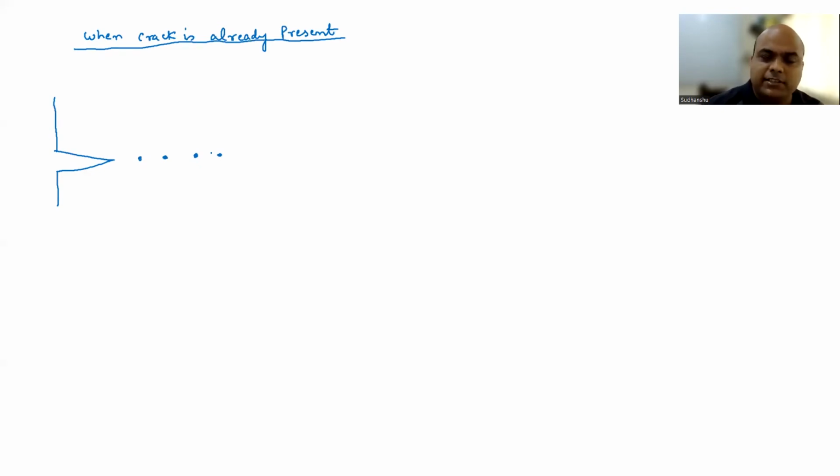Because of stress concentration in front of the crack tip. So what is going to happen? You are going to nucleate voids, right? At the locations of inclusions, either by debonding or by the fracture. We have discussed about that concept, right? And finally, they are going to merge or coalesce, and this crack is going to grow like that.